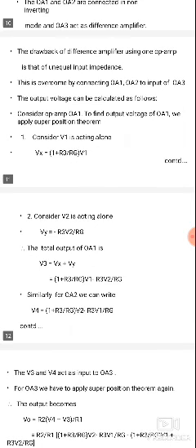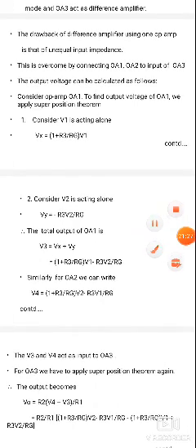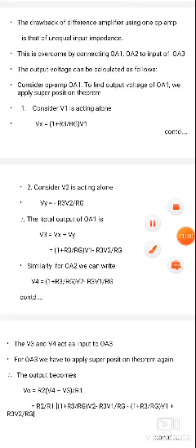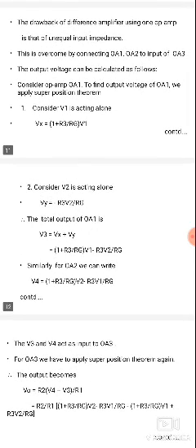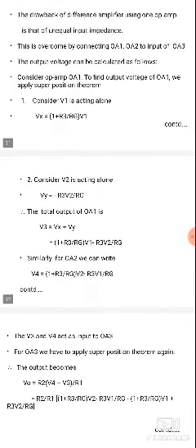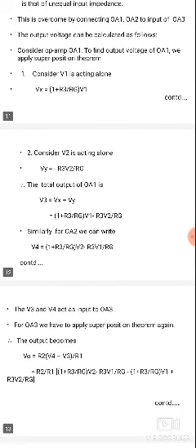The buffer type operational amplifiers eliminate the impedance matching problems. The buffer amplifier also has high input impedance, and it is mainly used for measuring and test equipment purposes. So the drawback of a difference amplifier with one op amp is unequal input impedance, which is overcome by operational amplifier 1 and operational amplifier 2 at the input of OA3.